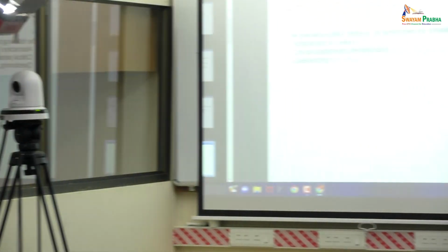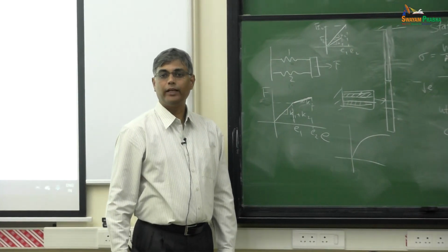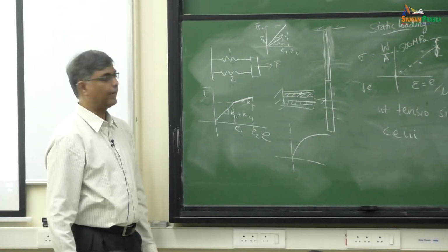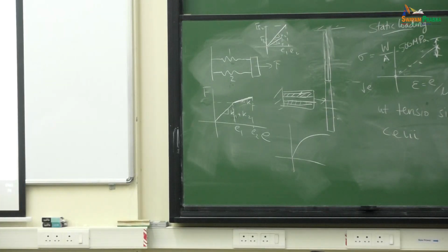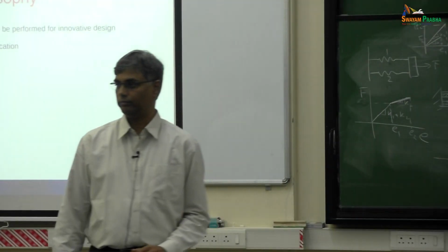Yes. But if you go till E1 and it breaks, then once you release the force, the next time you apply a force again, it will only go with K2, right? Excellent. Very good. So this is an intermediate state. If you go now and unload it, how will it unload? It will unload with K2. Yes, it will just follow along the K2 curve.